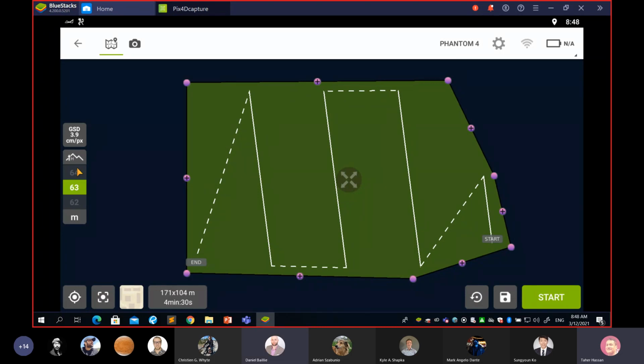The closer to ground you travel, the more depth your model will have. Whereas if you're flying higher, it's going to be flatter because it's more difficult for the program to perceive the different heights of objects, but it'll be a lot faster to do. So you kind of touch on it.